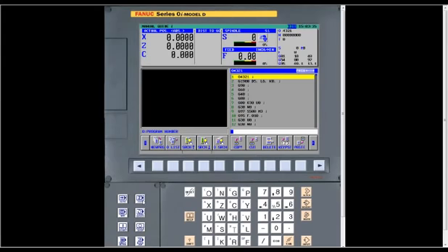Okay. Jody, I guess seeing that simulation sparked a couple more questions. One viewer says, I see the simulation is running faster. Can we get the actual cycle times? Yes. When you have it on an actual machine, now, because I don't have it set up on mine, when you go into the O list, if you go right shift for each, see how it has time here, cut time?